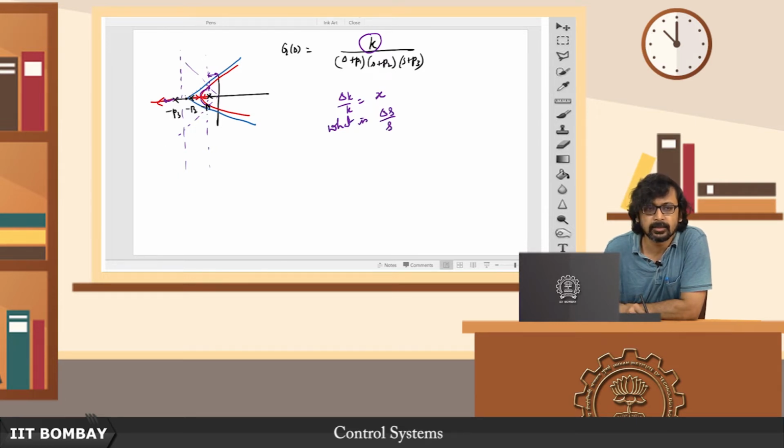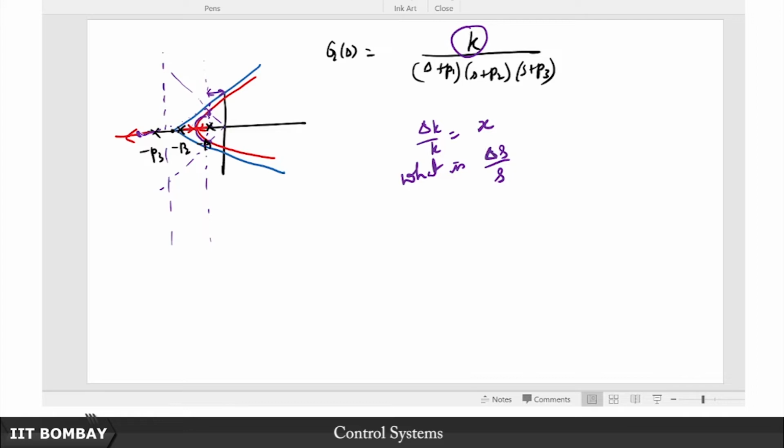So you just plug in this particular S here in this neighborhood, and remember this can be evaluated anywhere on the complex plane. It will in general be a complex number, but on the real axis you can clearly guess that it's going to be a real number, right? Because the closed loop pole is going along the real line here. So this is the question that is answered by the sensitivity, and you might see that maybe for a significant amount of change in K, this really hasn't migrated significantly to the left. And why is that important?